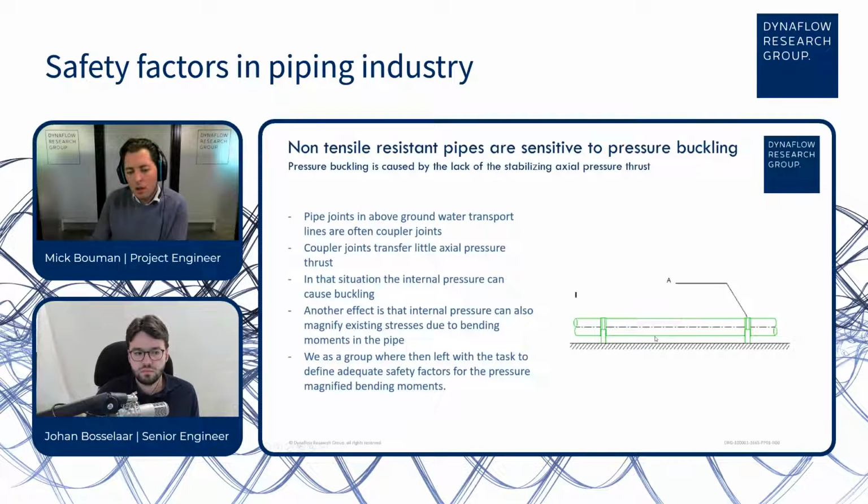If the pipe is under tension at the bottom, the amount of internal surface area is slightly larger at the bottom than at the top. That means that when you pressurize it, since there's slightly more area at the bottom for the pressure to act on, there is a net force laterally.